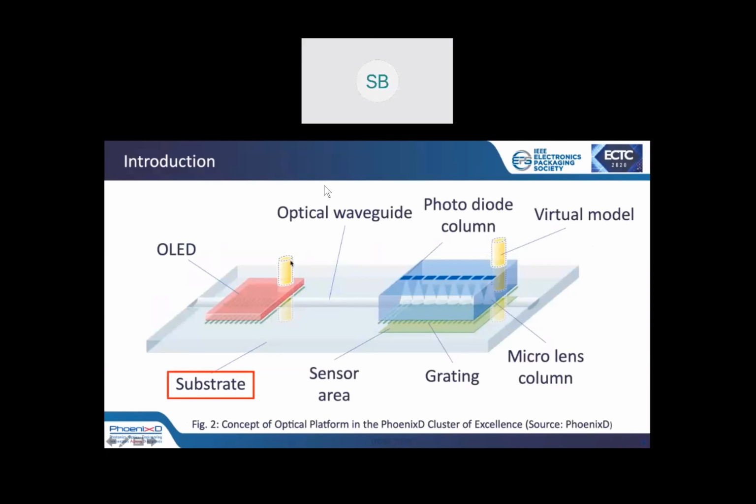If we look at the left graph, we can see different steel substrates, the C45 and the V2A. We have different layer heights of the electroplated structures, starting at 4.5 micrometers and going up to 75 micrometers. We looked at the surface roughness, and for the smaller structures it is below 20 nanometers on average. This surface roughness is sufficient for the optical passive components we address in this